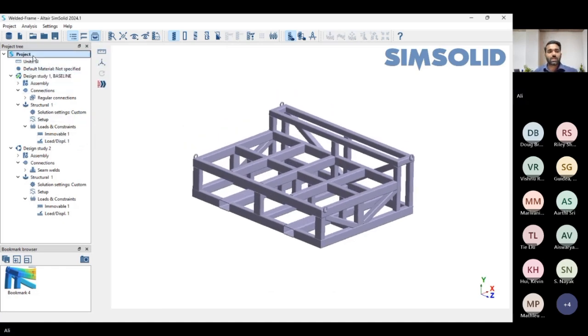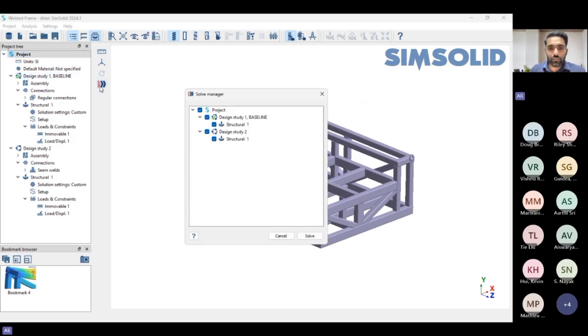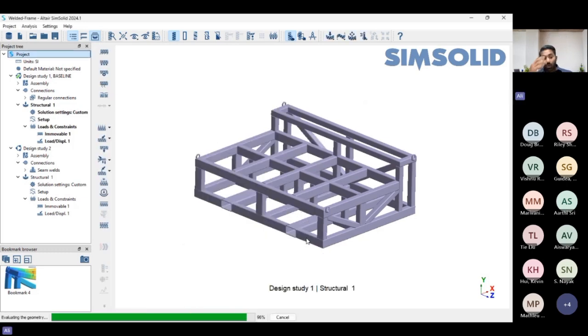Now I can just go to this project and just click on solve. Yeah, I just want to solve for all of these. Just click solve. Now in the bottom, you can see that the progress has started, right? So initially, as I mentioned, the very first step, what happens basically, it adjusts the parameter. It applies the equations in the whole of the body basically, instead of dividing into different mesh sizes, and then it goes on to repeat and try to see if it's able to decrease the error. And once the error is below a certain mark, it shows us the result.